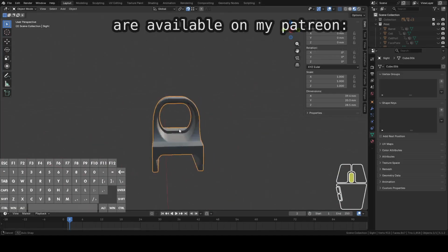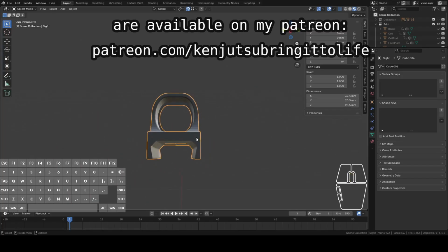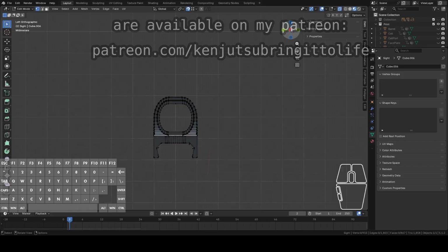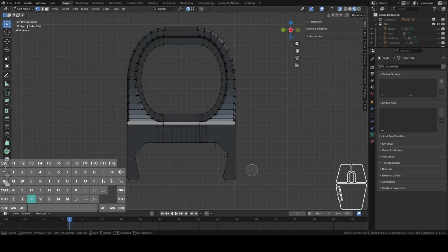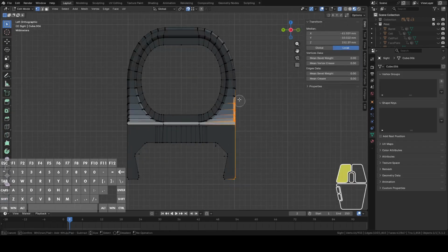Alright, we're back again with some needed edits. So after I printed the sight, after we reduced this area a little bit, this part broke, which means it's a bit too thin. So we're going to thicken that just a little bit by selecting all of these outer vertices. Right here, I got X-ray mode on, so I'm getting everything.